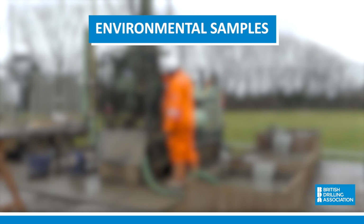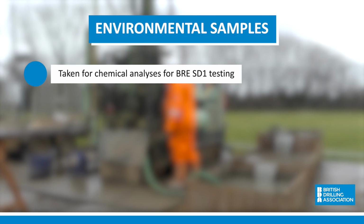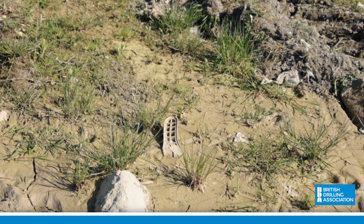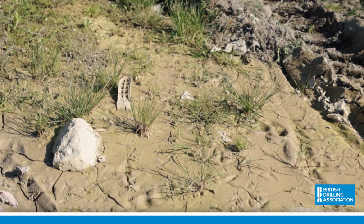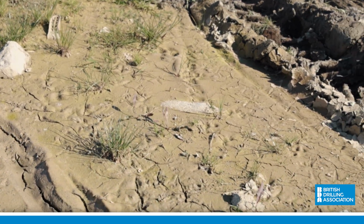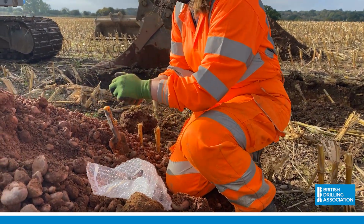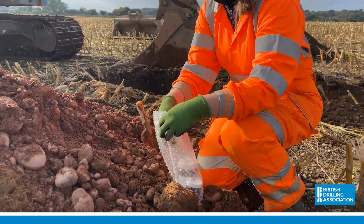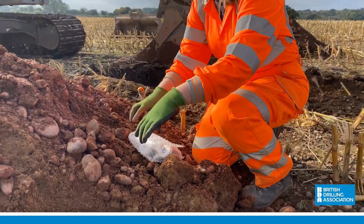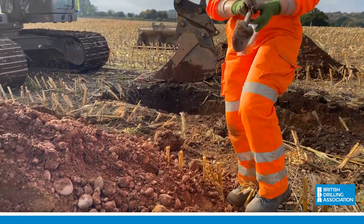Environmental samples are often taken for chemical analysis, which may be for aggressive ground, commonly known as BRE SD1 testing. More typically, environmental samples are used to determine the presence and concentration of contaminants in the ground. These samples have to be taken very quickly, stored appropriately, and transported to the analytical laboratory, normally at the end of each working day.